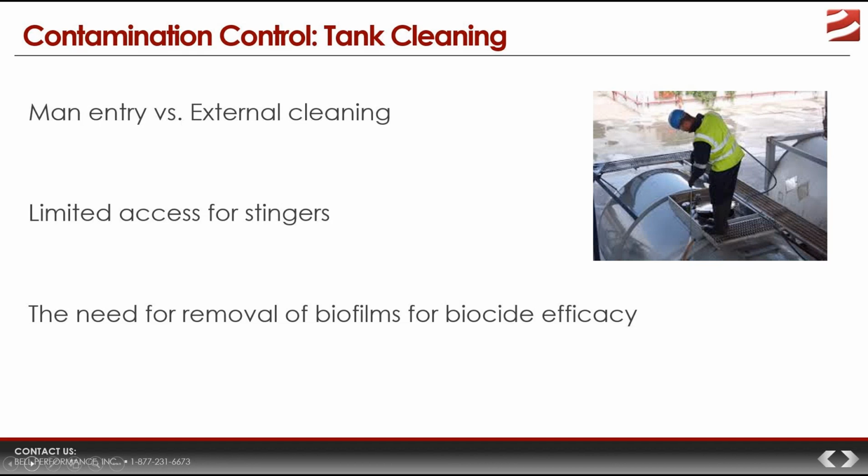Now, this is really important because remember, we said microbes love to live in the biofilm, so it's important to get as much of that out as possible. The greater the amount of biofilm that you leave in there, the higher the chance that your next step, your chemical treatments, may not be fully effective. So you want to have a good thorough tank cleaning and a good thorough dewatering.